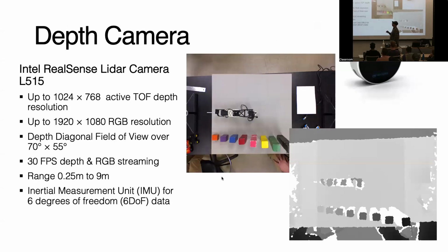In addition, in this lab, we're going to have a depth camera. So a depth camera is a special sort of camera. There's multiple ways to build them, and we'll actually cover more in depth later how these all work. But basically, what you have is an image, like a standard RGB image that you would see from a normal camera. And then you have another grayscale image where the pixels represent how far away the points in space are from the camera, okay? And so in this case, as the pixels get further away, they get brighter. So the blocks that are taller here are darker.